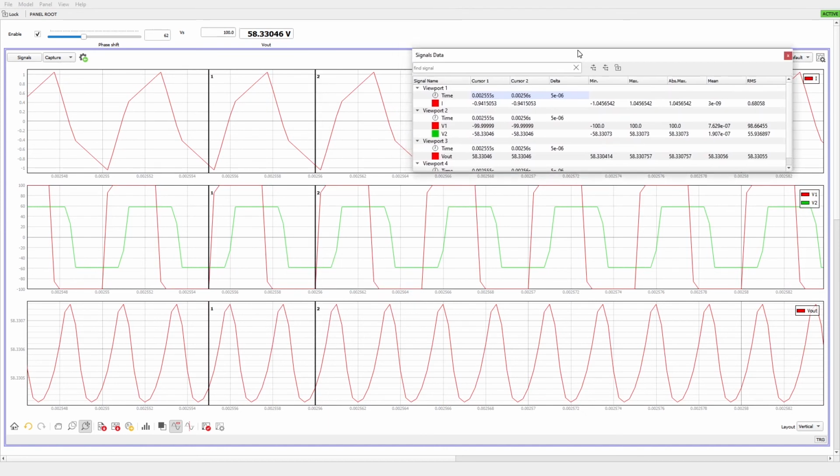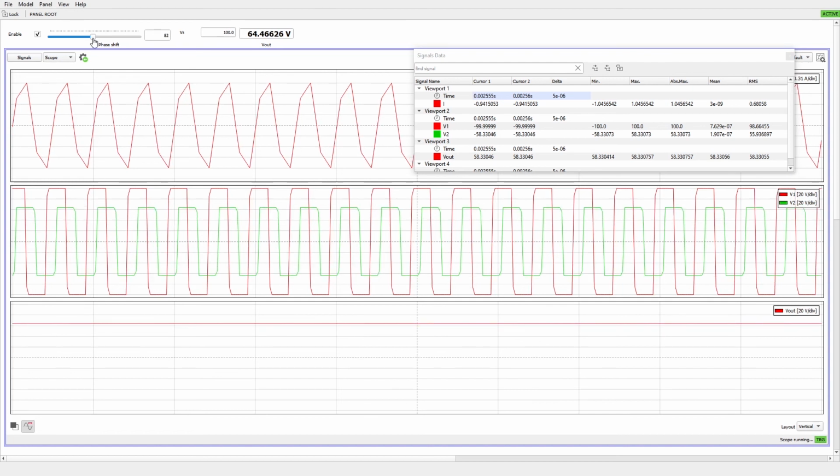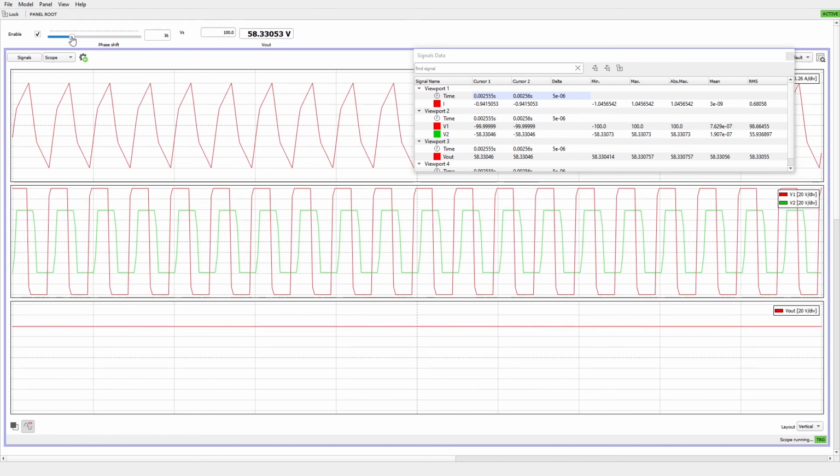To summarize, this new feature enables our users to utilize the maximum from our devices and to simulate dual active bridge and resonant converters with a much larger switching frequency. This ability was showcased on an isolated dual active bridge with a 200 kHz switching frequency.